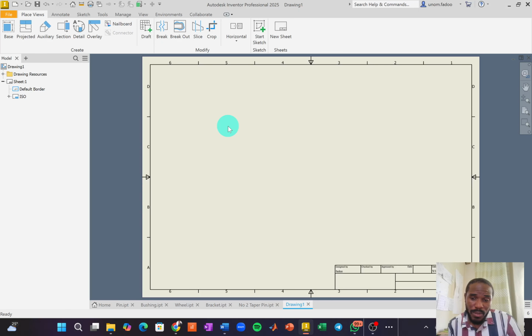In third angle projection, the plan is placed on top of the front view, and the right side view is placed on the right side. So you have the liberty of placing the views in whichever way you want to place them. Okay. So if we ask you to describe how to do something in third angle projection or in first angle projection, you need to know where to place what.